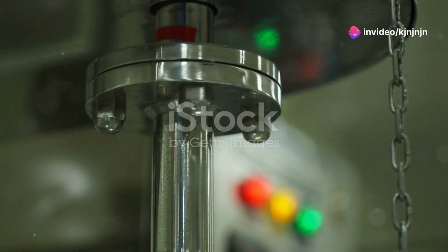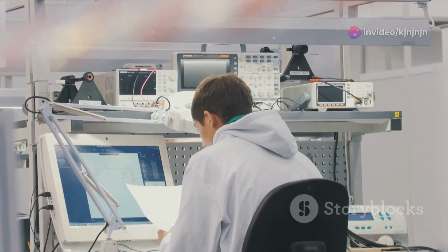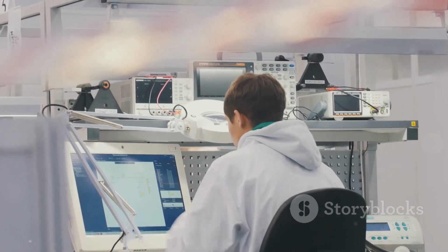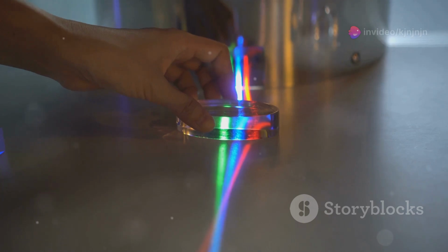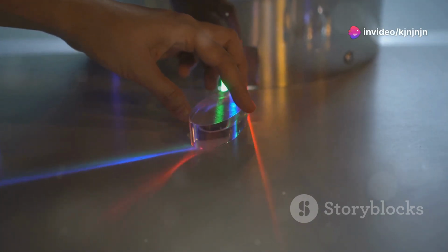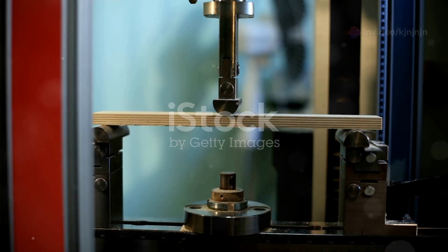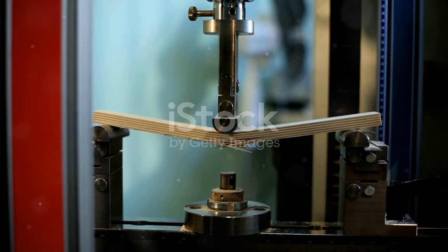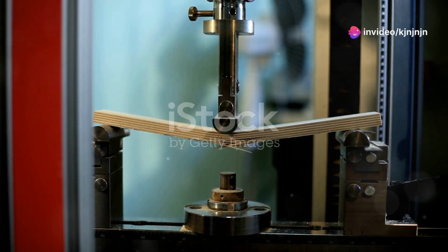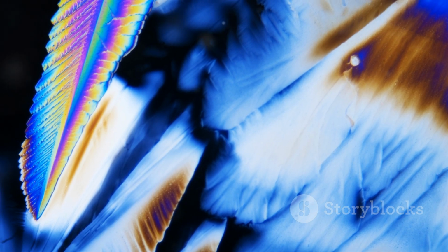Section 6. Photoelasticity: stress analysis through light. Photoelasticity is a powerful optical technique used for stress analysis. It relies on the phenomenon of birefringence, where certain materials exhibit different refractive indices depending on the direction of light polarization. When a stressed photoelastic material is placed between two polarizers, the light passing through the material experiences different phase shifts due to the varying stress distribution. This results in colorful interference patterns that reveal the stress distribution within the material.